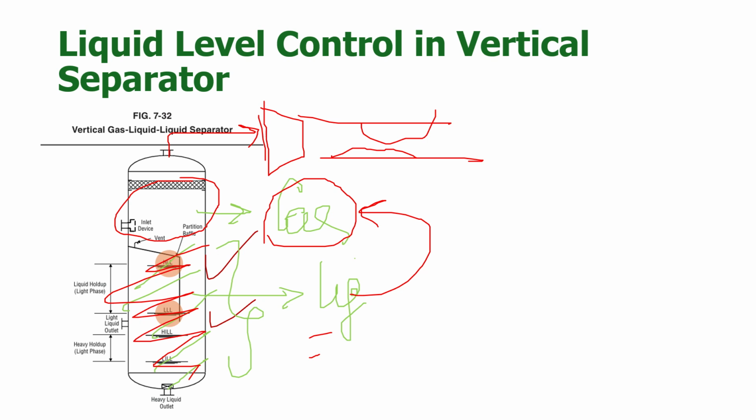So the gas particles will take some liquid droplets as well, and will go through to the compressor. As the compressor faces these liquid droplets, its machinery is not designed for this liquid. From its thermodynamics background, it's only and only designed for gas. That's why when it sees the liquid, it cannot transfer the energy of the liquid to the outlet. Therefore it starts to have huge vibrations, and you can hear this noise from the outside. So this is our recommendation to check from the process side, like the high liquid level if you are operating there, or if you have any issues with the inlet liquid level and so on.